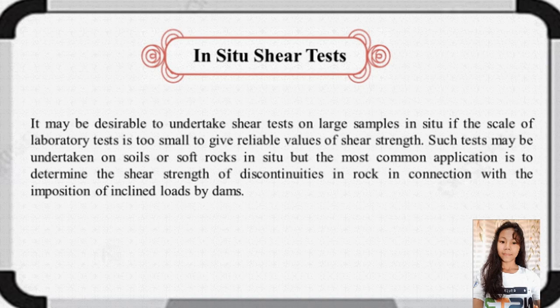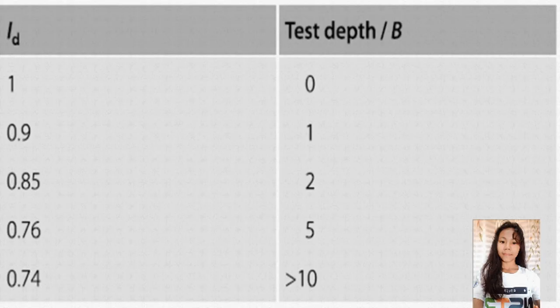It may be desirable to undertake shear tests on large samples in situ if the scale of laboratory test is too small to give reliable values of shear strength. Such tests may be undertaken on soils or soft rocks in situ, but the most common application is to determine the shear strength of discontinuities in rock in connection with the imposition of inclined loads by dams.